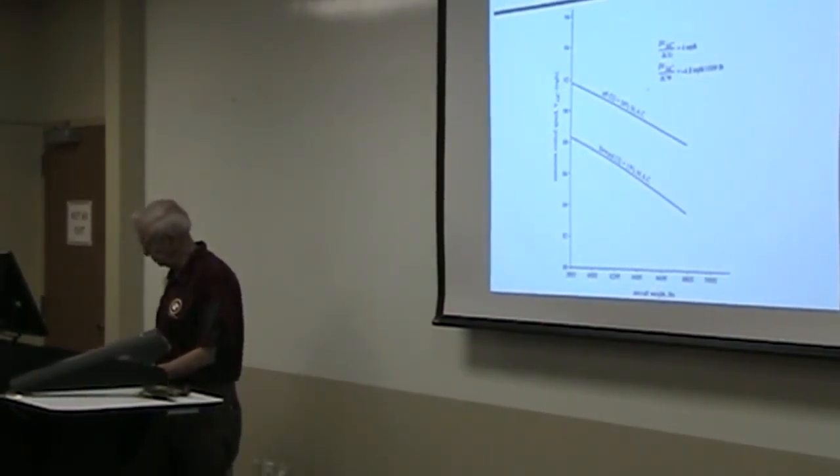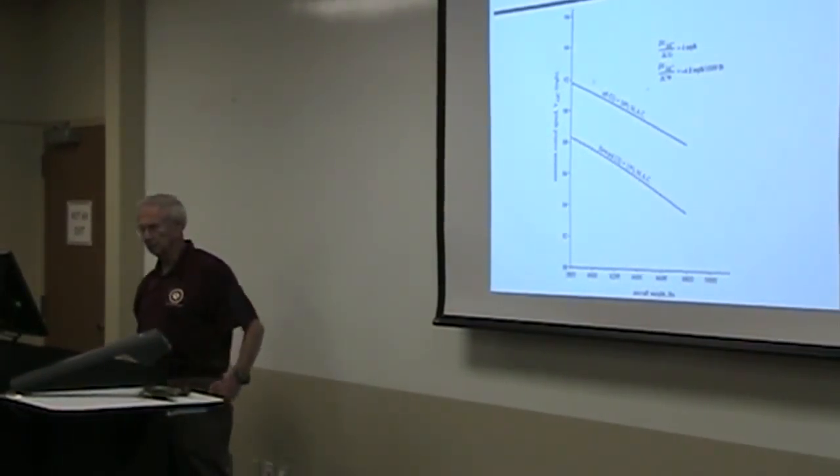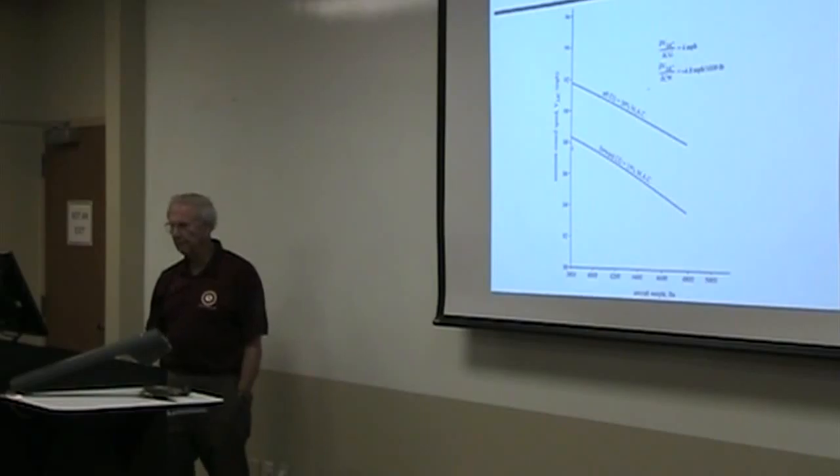Here's Les's curve, Les Bergen's curve that I was looking for a while ago. I got ahead of myself, I guess. But notice that here's FCG, 30% MAC. And notice that at 4,800 pounds, which was the gross weight on this airplane, that showed up at 88 miles an hour. Okay, take that across, it's 88 miles an hour.